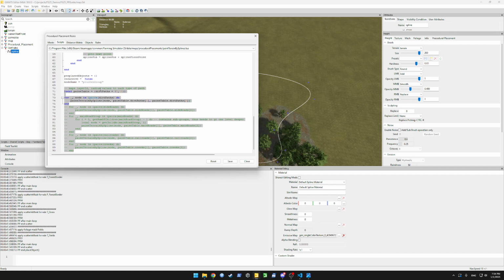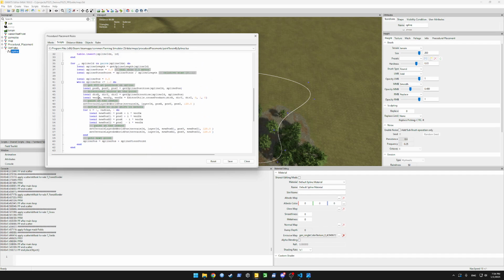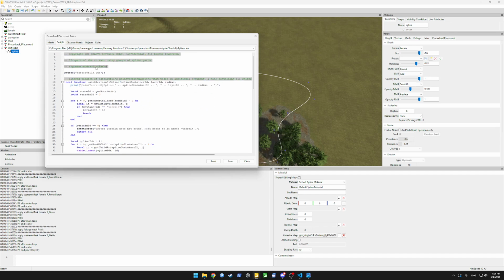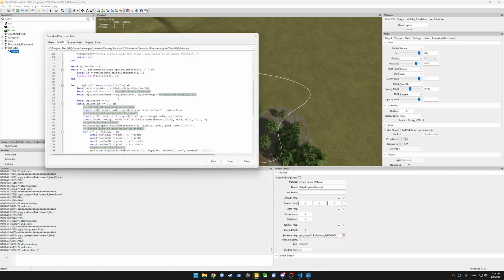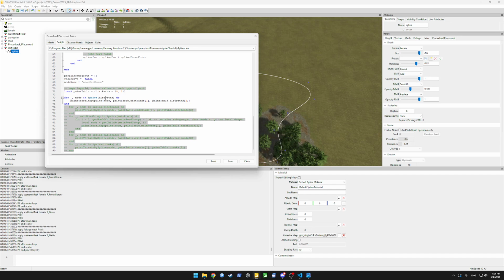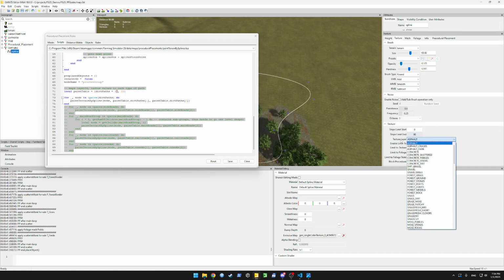Actually, the paint table is also used, and you don't need all the arguments. I'm just going to paint one road, and that's a dirt path. For every dirt path, we're going to use this material, and we're going to paint it in this layer. We're going to paint this layer 0, so for example texture 0 in my case is asphalt. We're going to paint asphalt with 2 meters width. That's our dirt path. We don't want asphalt.